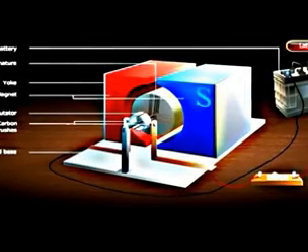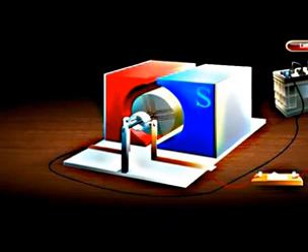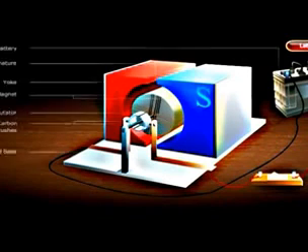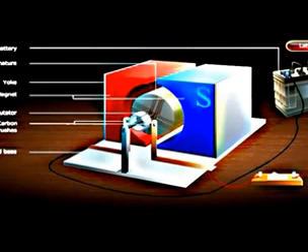The motor is a device that provides mechanical energy when electrical energy and a magnetic field are supplied. A simple DC motor consists of a rectangular wire of many turns wound on a frame. The frame is mounted on an axle between two magnetic poles. Current is passed through the coil via two brushes, which are pushed against the split ring commutator attached to the coil. The commutator ensures that the direction of current in the coil reverses every half cycle and the coil rotates in one direction.